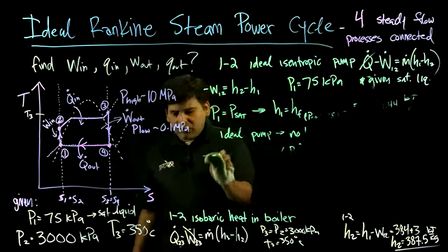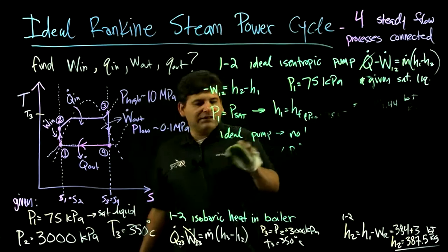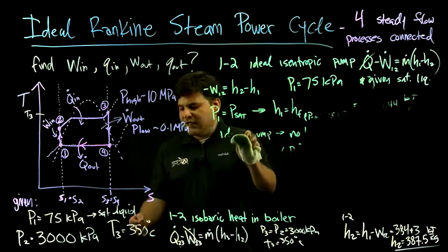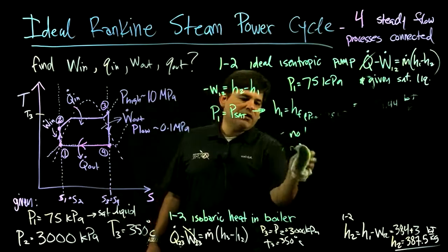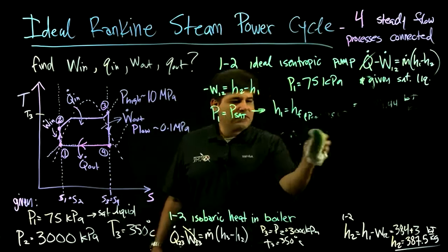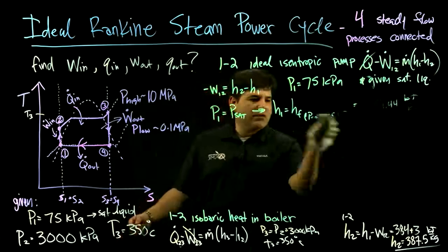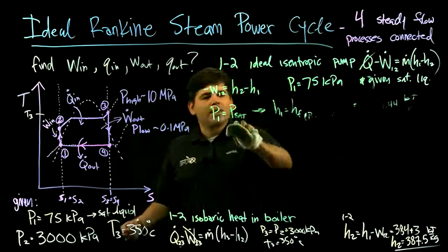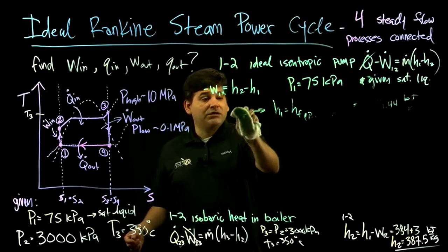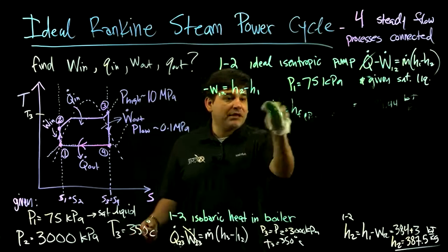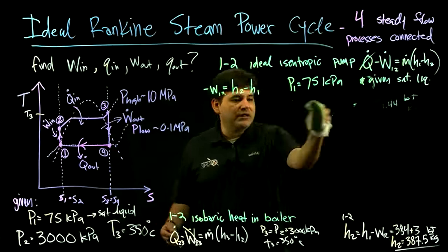So yeah, spoiler alert: if we look at P3 with T3 at 350 Celsius, Tsat is less than 350. So we are superheated vapor. I don't know what Tsat is exactly, but that's the test we did. P1 is known, P2 is known. That means for an isobaric heat transfer, we also know P3.